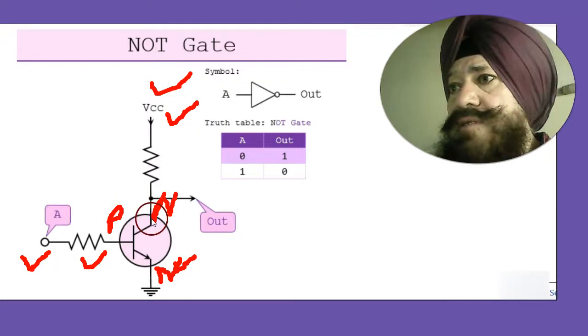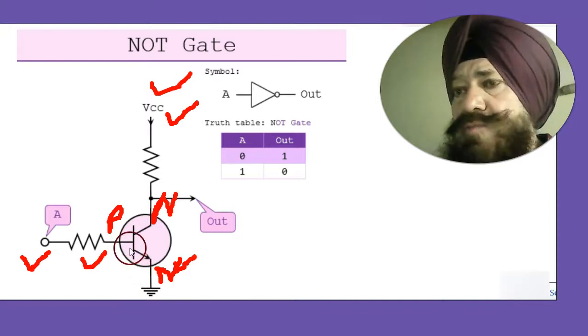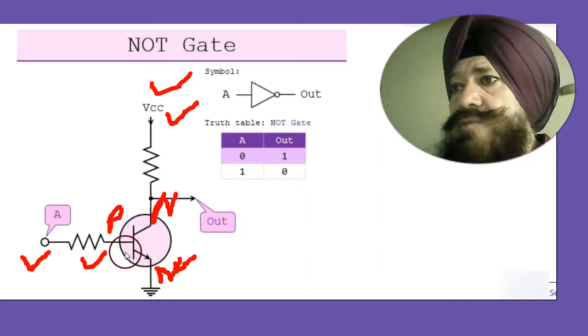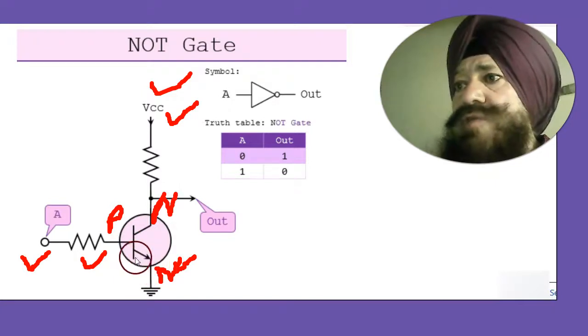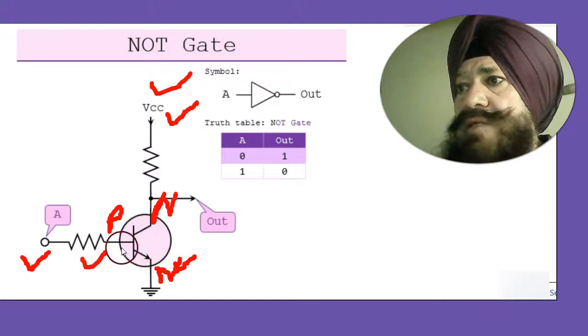Now as the emitter is grounded, or at 0 volt, a small non-zero reverse current is flowing through the emitter to compensate the diffusion current, and an equal and opposite current flows in the base-emitter junction, minus ICO.